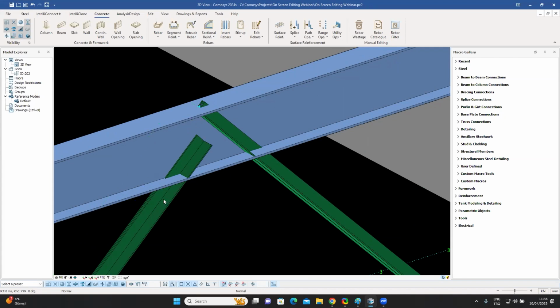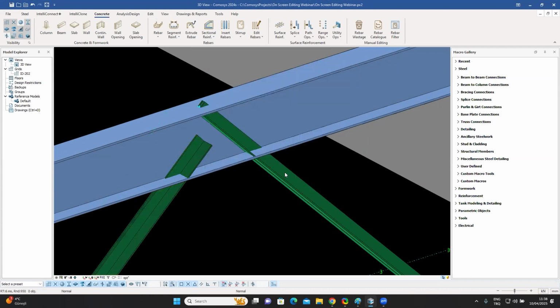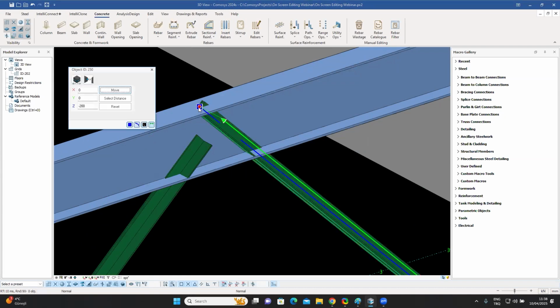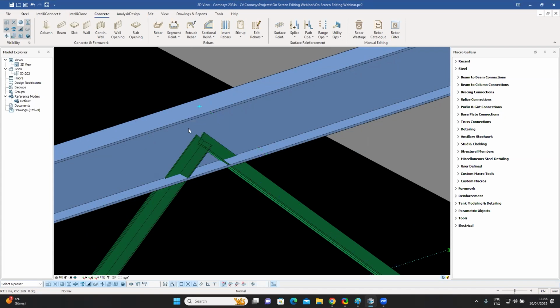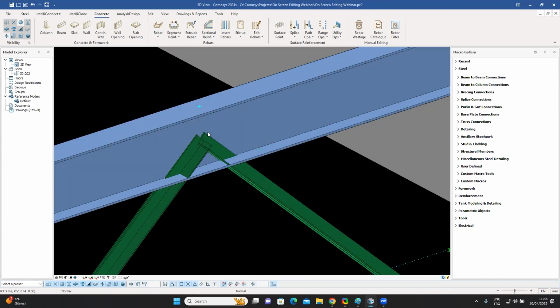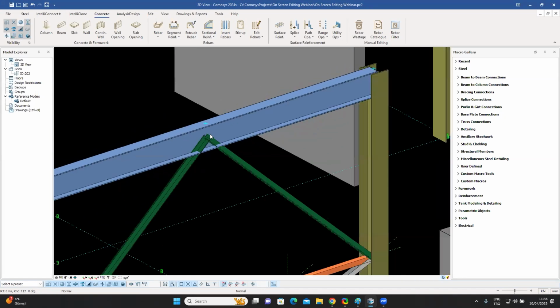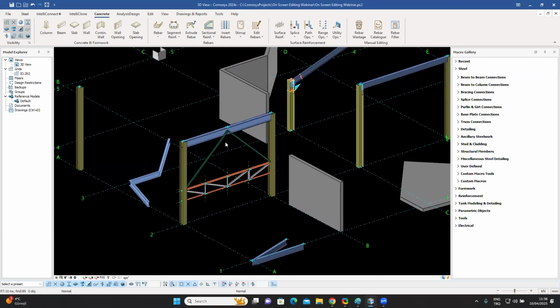And this appears in the form of these numbers, which are difficult to calculate otherwise. You can do them like this as well, but it's much easier, for example, select this one, then go in and select the adjust button handle over there and say move. And now both the vertical bracing have been moved to that point while my finite element model has been maintained. So this is a very useful way of moving around the offsets of your frame elements.